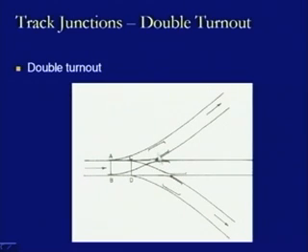One check rail is provided here, another on this side, and if needed the smaller one can be provided at this location too. So, that is how they are crossing each other on this side, and there will also be a crossing at this location, as you can see here. So, this is a V, and at this V again there will be a pair of wing rails provided like this. So, this is another place where the crossing will be provided. So, we have three crossings, and depending on the flexure, this crossing may be in the central position, or it may shift towards either the left or the right.